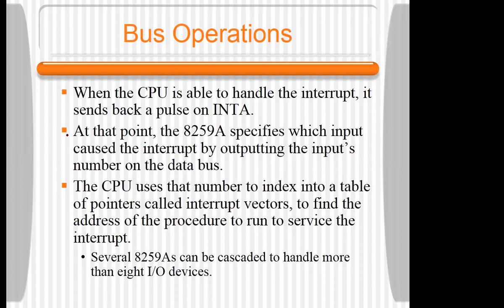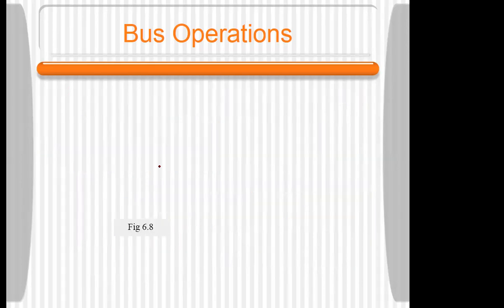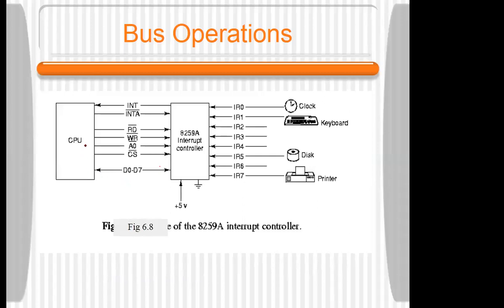So that is what happens. An interrupt is given, then the device address is given to the CPU, then that will also go to a vector table which shows what type of procedure should be executed in accordance with the interrupt that we have received. So we have the CPU, then the interrupt lines, then this will be the interrupt controller, then it is a table of the interrupt requests.